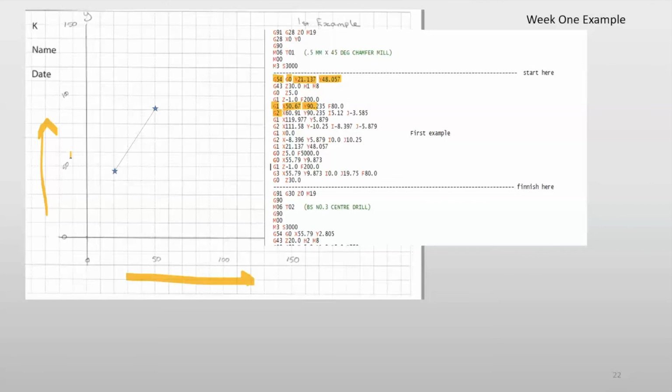For our arc, I would expect a P2 from A, you're going to go to a second point and a center point of it. The first one was absolute, so from the point 0, 0 you find point 60 and 90. If you notice, Y is constant, Y didn't change, so only X is changed. So find that point.